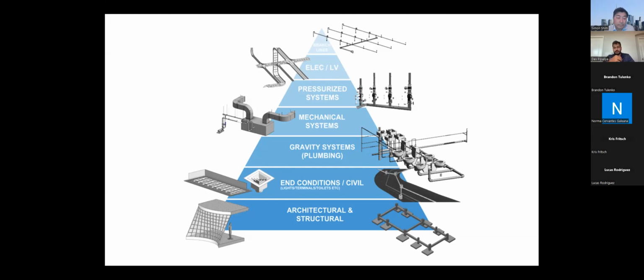But as the scenario changes, a lot of things change. If I was doing a project and in electrical there's a cable tray going, I would actually give it more priority than the mechanical system, just because the electric cable probably has 10 to 15 conduits going inside it. So instead of moving all those 10 to 15, it might be easier to move a small duct. Things change as the scenario changes. That's the key over here, but this is the base that's being followed in the industry.